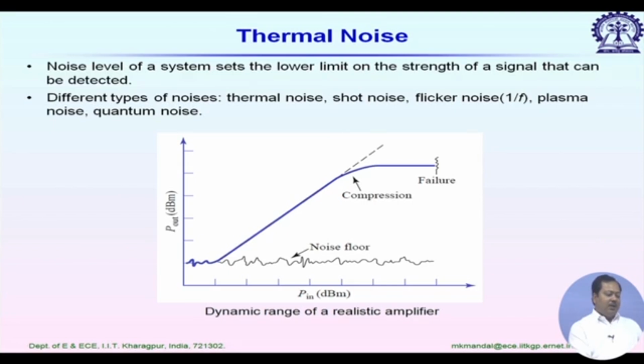If we keep on increasing the input power level, at some point the device saturates. So it determines the highest input power that can be applied to this particular component, or it can also be any instrument. And again after that, if we keep on increasing the input power level, at some point we might burn the component. So we call that point the failure point.